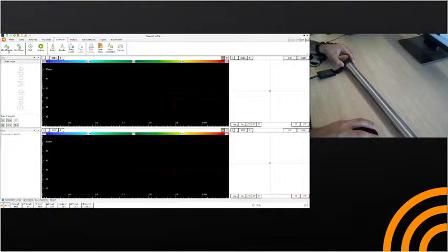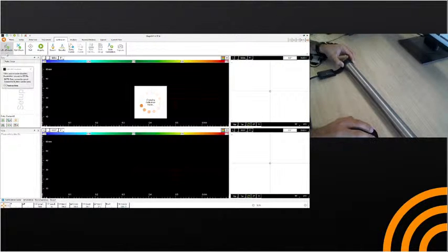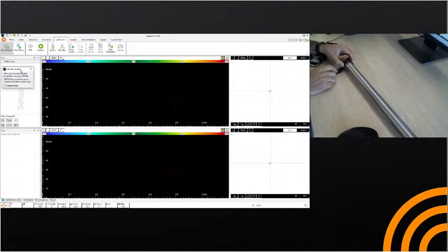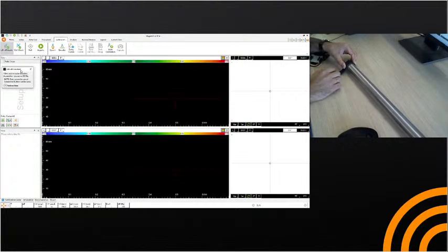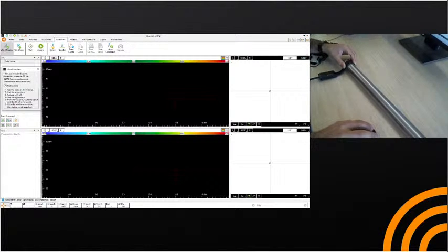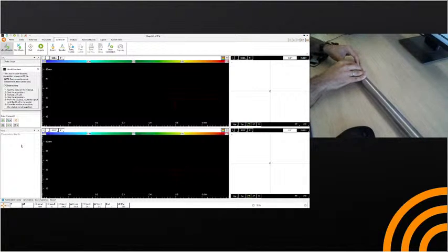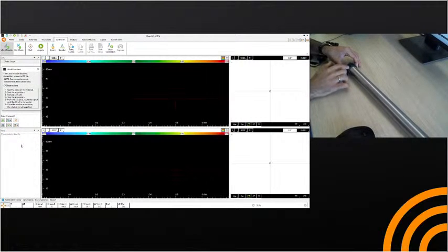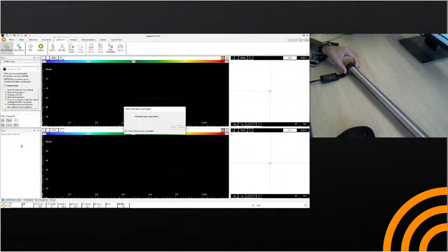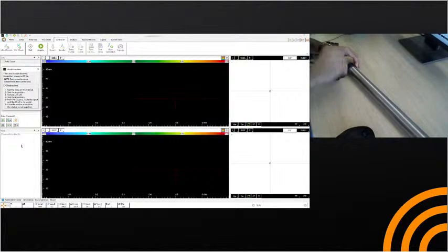On the software, you click Liftoff Assist. So it will switch the mode. Usually when you want to perform the liftoff, you should change your scan mode to keep it in clock mode. In this case, this feature will automatically switch between modes, and it actually has the instructions or the steps needed to perform this liftoff. So here I'm balancing. Like I said, always balance on an area where there's no defect. So I'll hit balance and start acquisition.